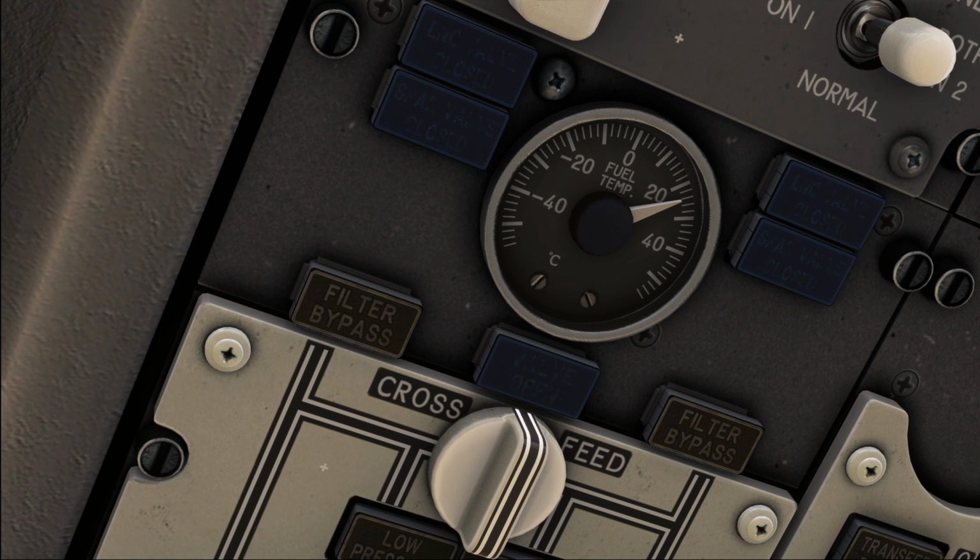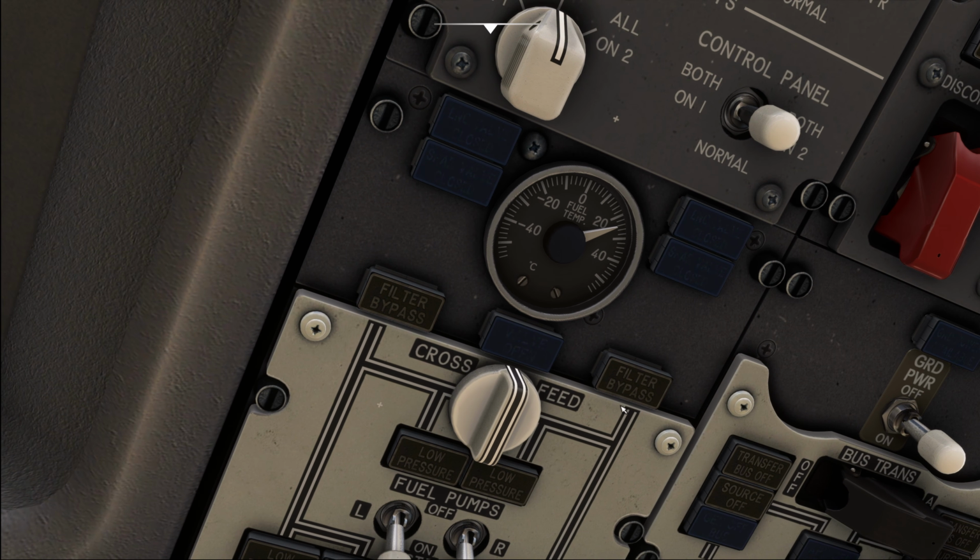On the MAX, this has been enhanced to an impending or actual fuel filter bypass due to a contaminated filter, and if both lights are illuminated, then both lights will remain illuminated until the engine has been shut down on the ground. This might, for example, be the case if you have contaminated fuel on board, and in this case the lights are going to stay illuminated.